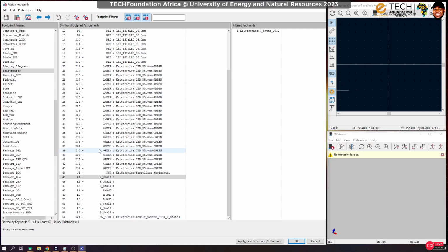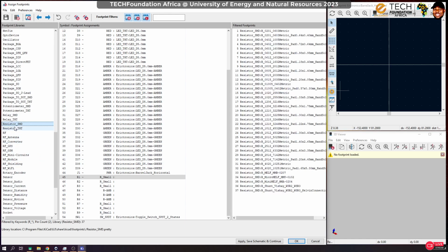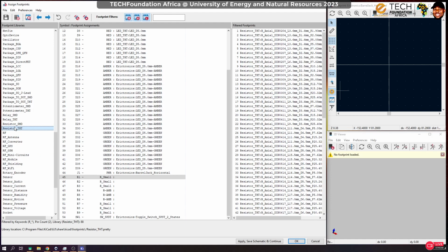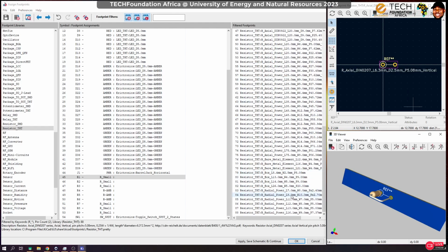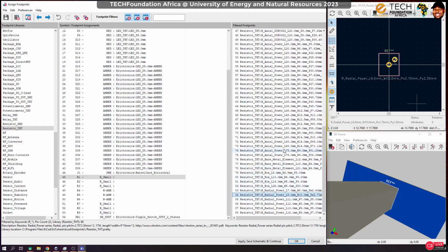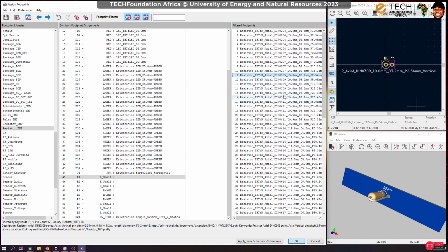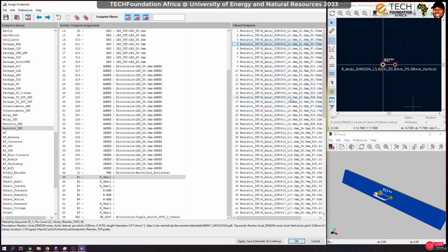When you go to resistors, you should find two versions, SMD and through hole. We are working with through hole, something that we have to drill a hole and push it through, okay? So for our resistors, we need a quarter watt resistor. We've already checked the dimensions and you can see that there are various shapes, but we want something axial and horizontal.